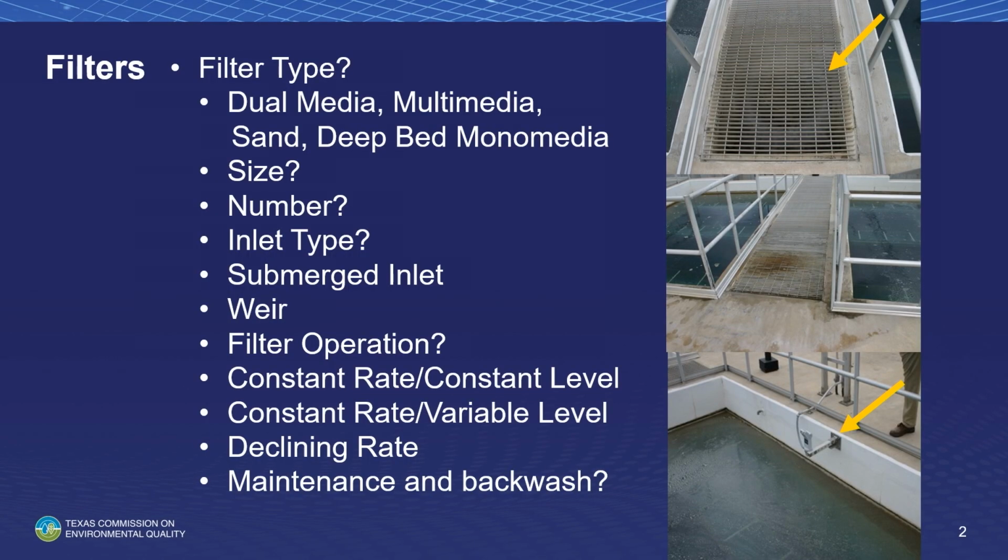And invariably, the lines have sags and dips in them. And anytime you have a line that has a little sag in it, you're going to get sedimentation in there, okay? It's just a fact. So they don't install these lines like they're supposed to, and that's another issue that you can find in a filter gallery. Testing, well, there's always an issue with maintaining the turbidimeters.